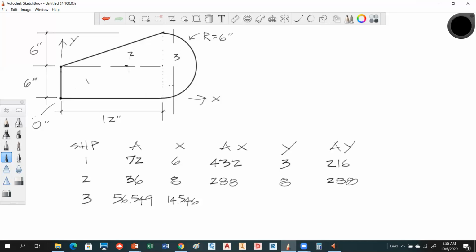So we're going to take this distance, which we calculate, 0.4244R plus 12, and that's where I came up with this. So this distance right here turns out to be 2.546 plus 12, which gives me the 14.456. Does that make sense now? I got you now. Okay. Cool. Perfect. Seriously, that's going to be your hardest thing.